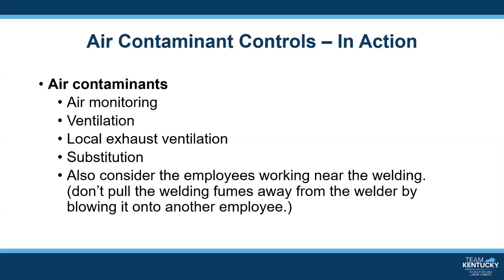And then you must follow the regulations found in 29 CFR 1910.134, which requires a respiratory protection program. When welding with certain especially hazardous materials, a powered air purifying respirator might be required. That is called a PAPR. When welding within a confined space under certain conditions, airline respirators with an air supply hose might be required.